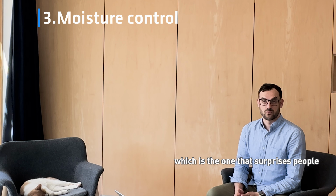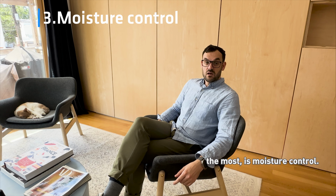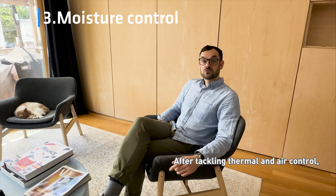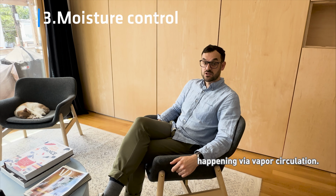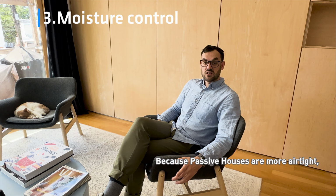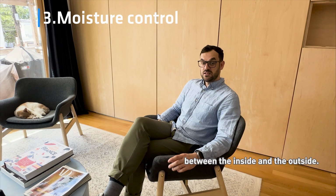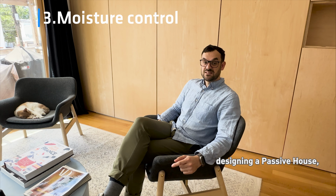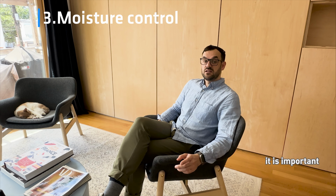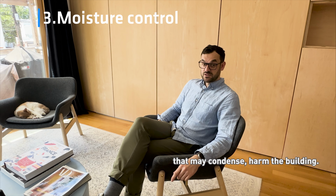The third principle, which is the one that surprises people the most, is moisture control. After tackling thermal and air control, we need to address energy exchanges happening via vapor circulation. Because passive houses are more airtight, less humidity is transferred between the inside and the outside. As a result, when designing a passive house, it is important to prevent high levels of humidity that may condense and harm the building.